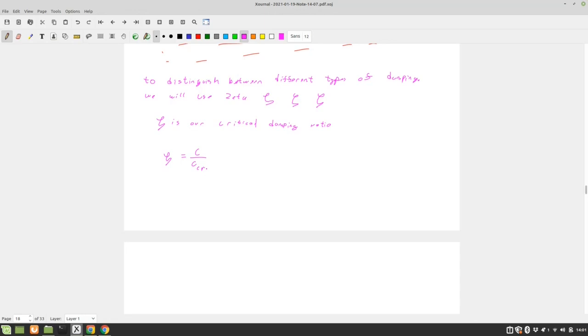the math and the communication part of it, you could say, I have a critical damping ratio of 1.2. And people will know, oh, that's slightly overdamped, right? Instead of having to give them the CCR, like your critical damping value, and then your actual damping value, and then your mass and your stiffness, and letting them figure it out, right? So critical damping ratio is us pushing that all into one index, right?